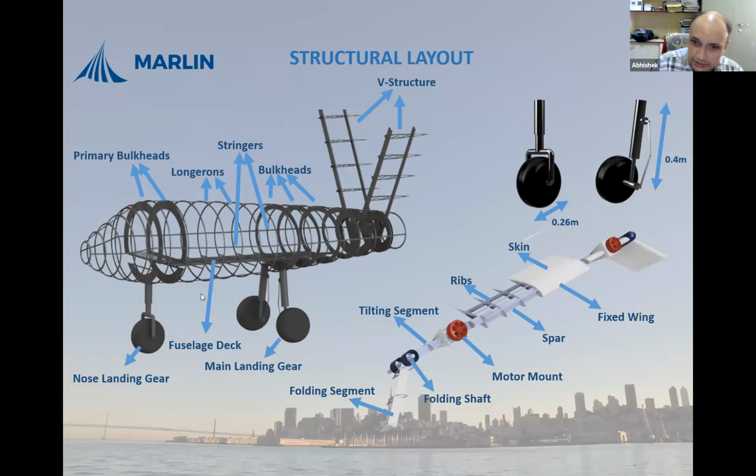So here are some more details about how the internal structure of the whole fuselage was thought about. There are bulkheads, longerons. These are all structural aspects, because finally the structure has to be designed in the most efficient and optimal manner. A lot of innovations happen there. For example, when the Maryland team was trying to build a human-powered helicopter, making the whole design ultralight was super critical, because every gram of weight makes a difference of a few seconds in the whole flight time.